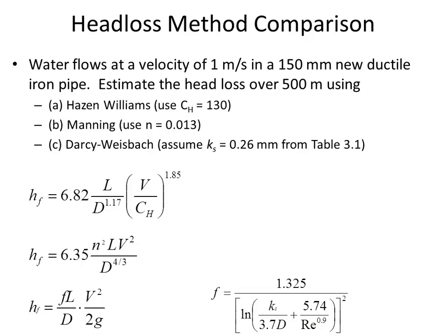And so it might be here that because the water is in contact with the entire pipe, it's overestimating the amount of energy loss because there's a really long wetted perimeter. But the velocity here is relatively slow. 1 meter per second is a pretty slow moving velocity. And so it might be the combination of those two things.